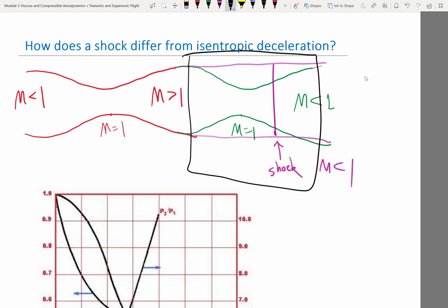So what is the total force from the fluid, just to think of it as a rocket nozzle? Actually, this is like a reverse rocket nozzle. This is like a rocket nozzle where the flow in the combustion chamber is subsonic, and then the nozzle accelerates the flow to supersonic speed, right? So this is like a reverse rocket nozzle, and what is going to be the force from the fluid to the nozzle?